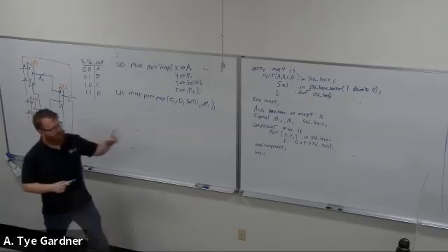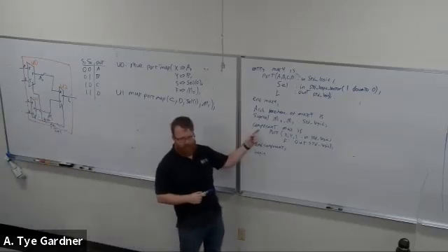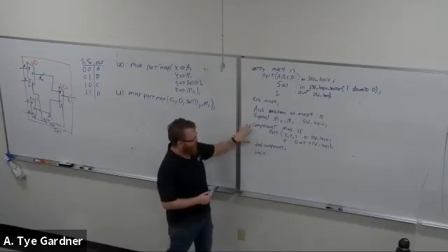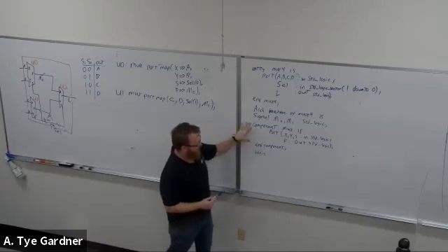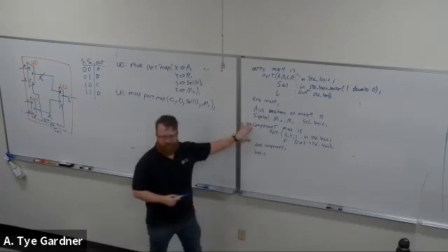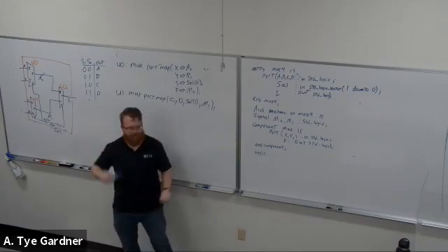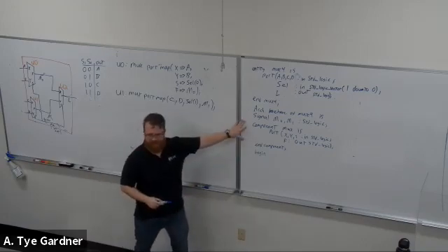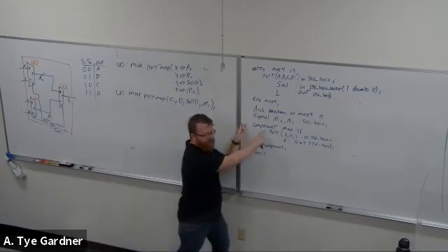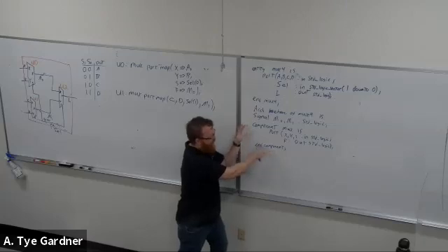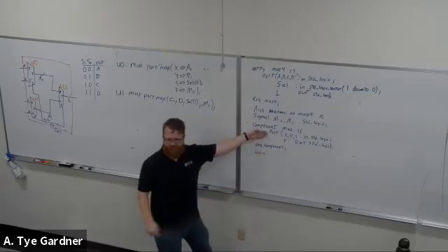Right, but you should always, this should always be the same, by the way, your component declaration, not because it's strictly enforced, but because if you're typing this whole thing out, you're wasting time because you can go to the entity, copy, paste the entity, you change the word entity to component and add the words end component instead of end entity name, right? Then you copy and paste it, there is no room for errors in your code.